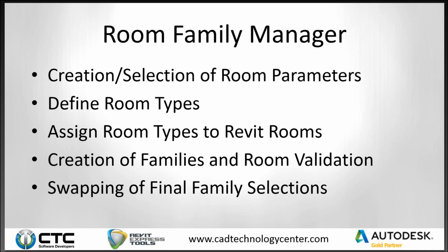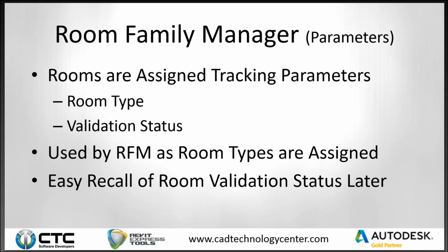So first of all, the workflow goes like this. With the Room Family Manager, you have to make sure you have the correct parameters for tracking the room type and the validation status of the rooms. This is used by Room Family Manager. As room types are assigned, it assigns the room type. And then later on, as you're working through after assigning room types and working with them, you can validate them over time, and you can easily recall that information back up into the Room Family Manager tool. We'll take a look at that in a moment here.